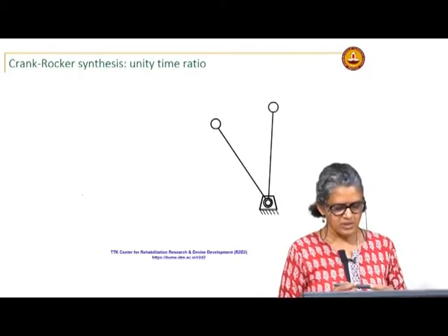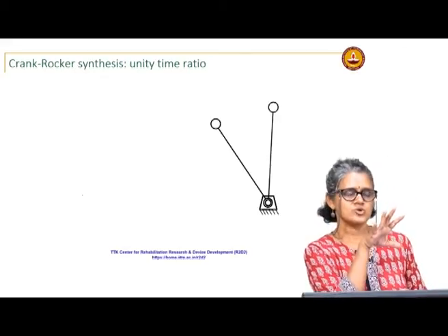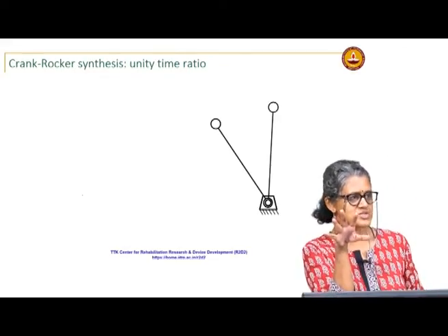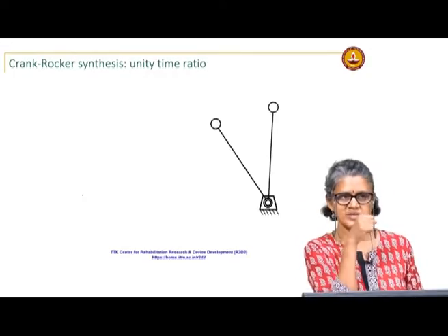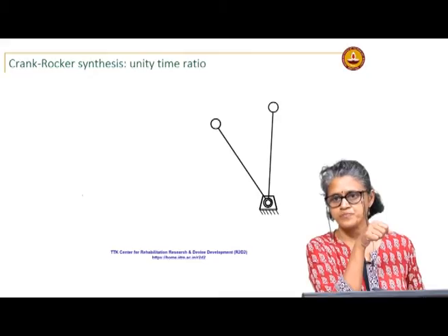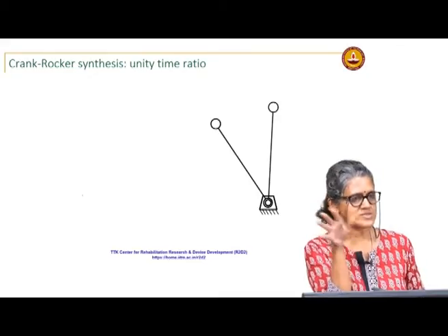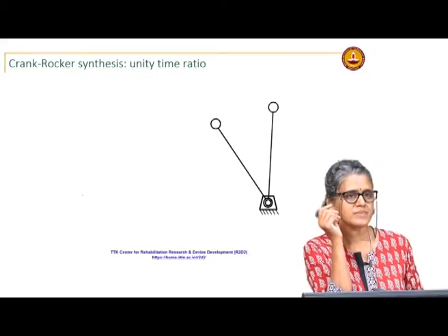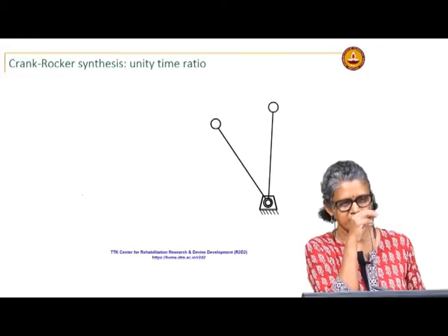Okay. So now, two position motion generation, you can solve it without a linkage by just pivoting at the pole, okay, or you can use a 4 bar or a slider crank or double slider, whatever. Mostly we will look at the 4 bar.